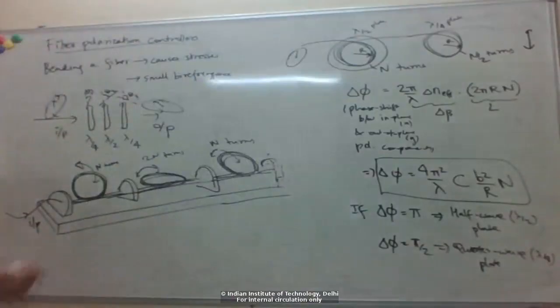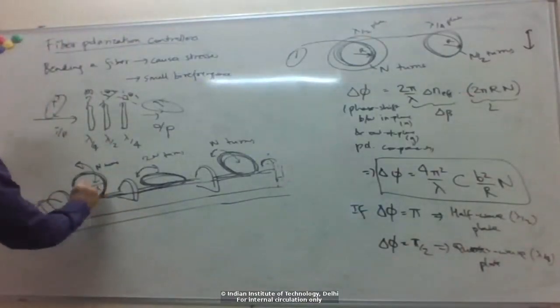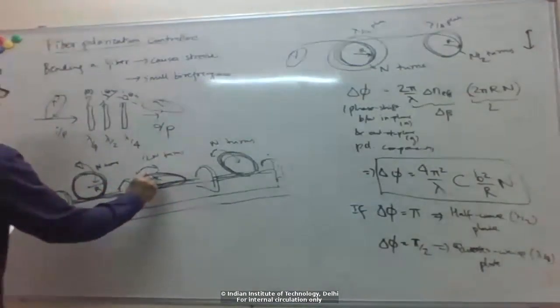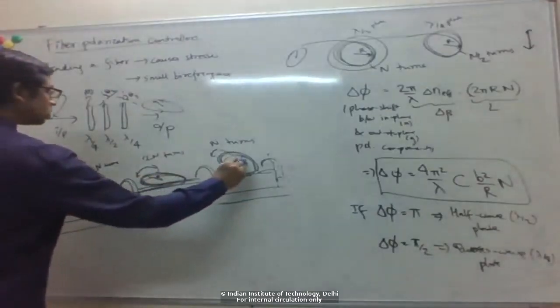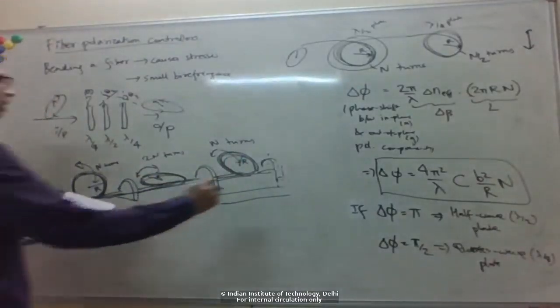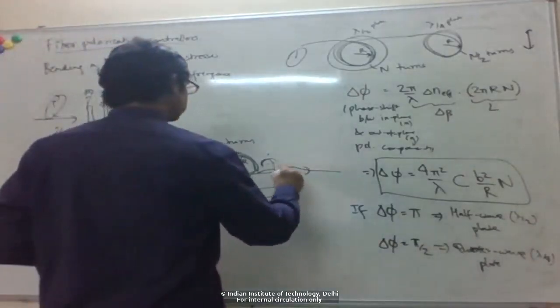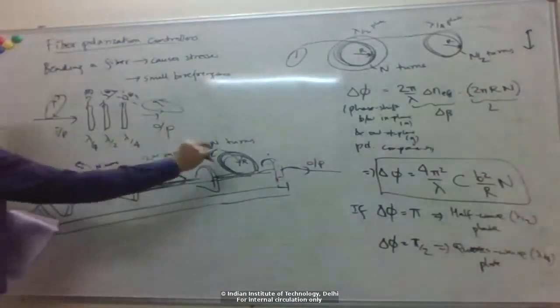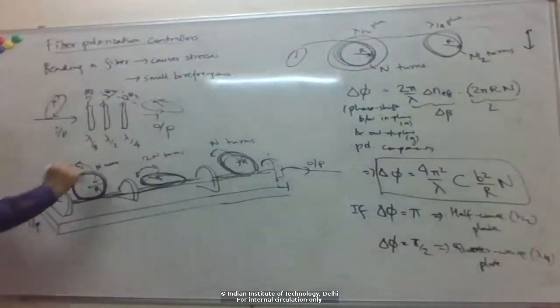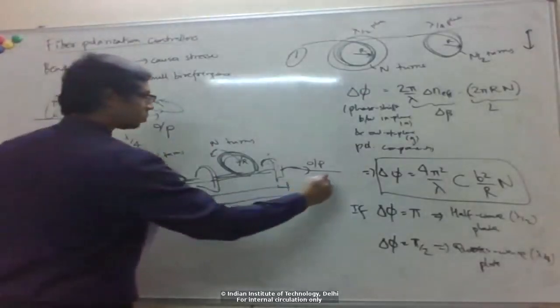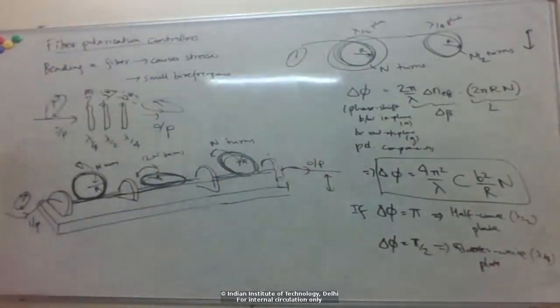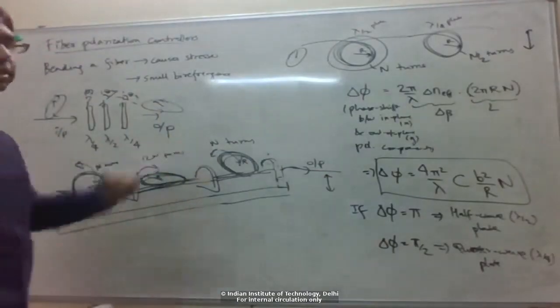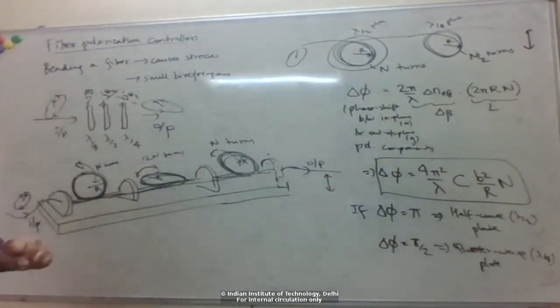The typical size of these paddles, the radius, would be a few centimeters. And then the output comes out from here. By adjusting these paddles, by setting them at some angles, you can change the polarization from some arbitrary input polarization to what polarization you want, which is equivalent to rotating in place.